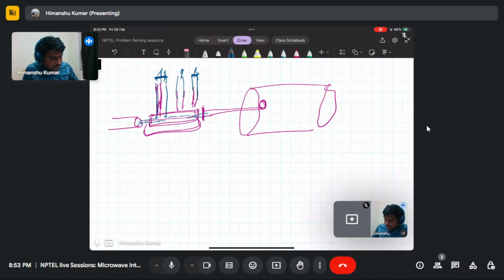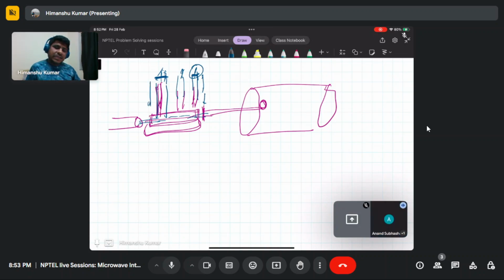Now if you use only this transmission line, you can't tune the resonance. To have tunability, you connect movable stubs that you can match with. So at any frequency, any impedance you can match. You don't need to use different stubs, you just need to move them around.